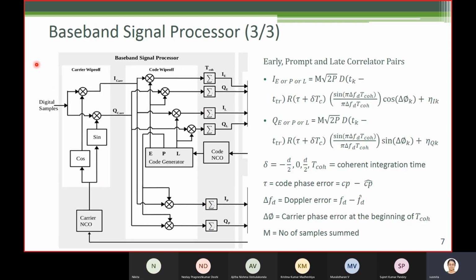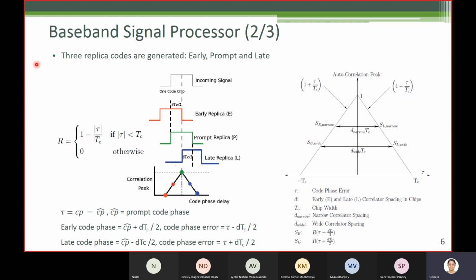Now when I say code phase, what exactly do I mean? See, so this is an incoming chip, right? Now first time when you are trying to acquire a satellite, some point in the code period has come, right? We have a number of chips in a code period, capital N chips. In case of C/A code, we have 1023 chips in a code period. First time when the receiver is trying to acquire a satellite, some point in that code period has come, right? And we know how to find the phase of that point.